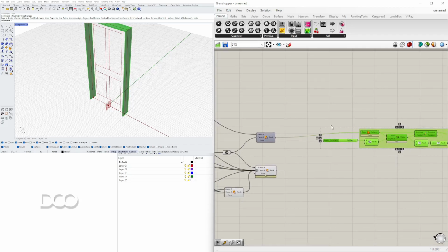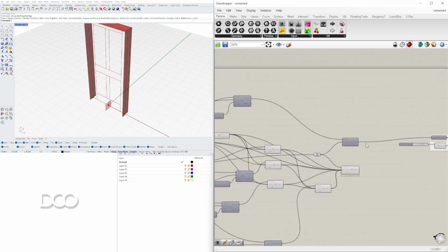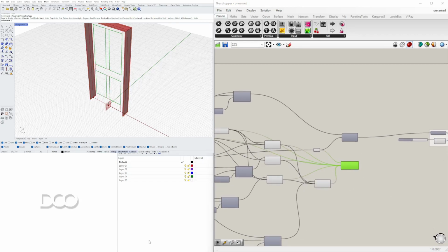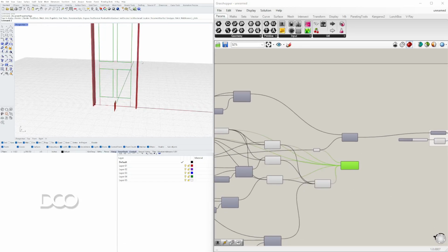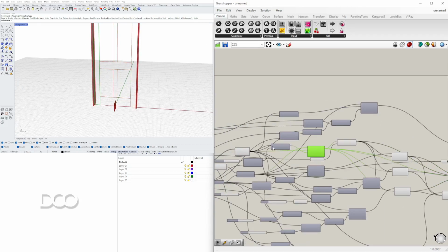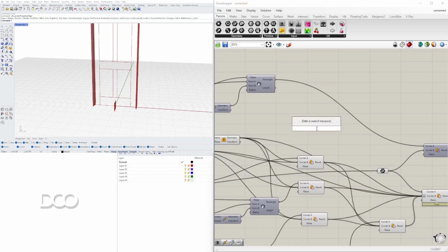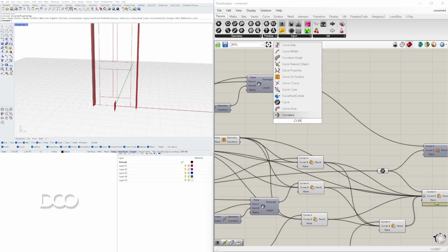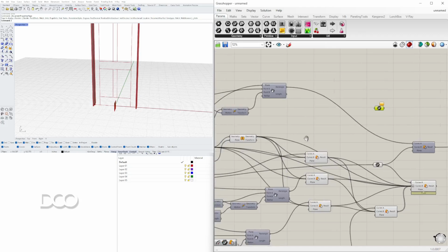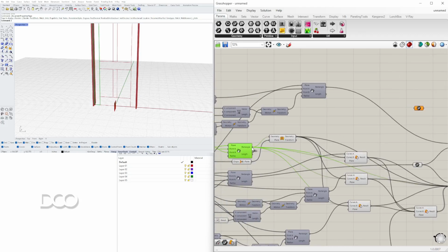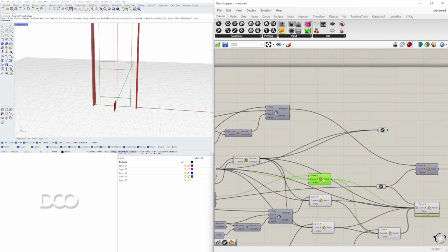We're going to do the same thing to the side panels. So we'll go here to the side rails first, this one and this one. Bring those both into a, well, technically we want to bring all of those into one component because they're all going to be extruded the same amount. We can go rectangle into this one and hold down shift and add additional inputs for the ones that I want to extrude at the same time.